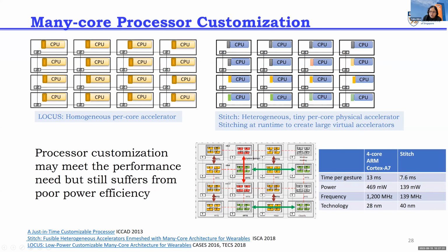And in order to do that, basically, you have to have 3 different things. So first, you need to embrace the parallelism, because as I mentioned, unless you have parallelism in your application, you are not going to benefit. You need to keep the hardware really, really simple, because you want to make it low power. That's what we care about in edge computing. So the hardware cannot do a lot of complex things. It needs to be really simple. And then you have to expose things to software, because somebody needs to do all the hard work. We are moving that hard work from the hardware to the software, or in particular to the compiler. Okay.